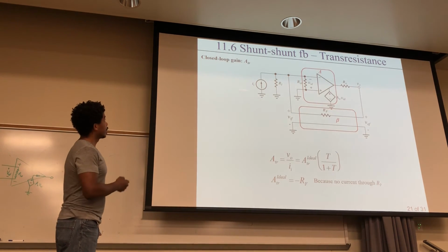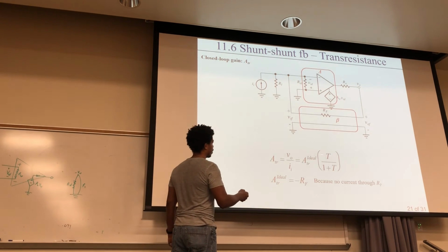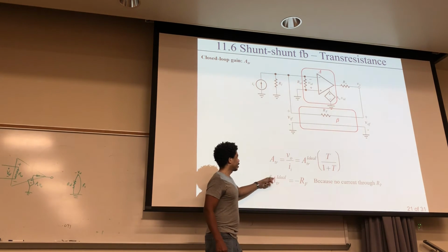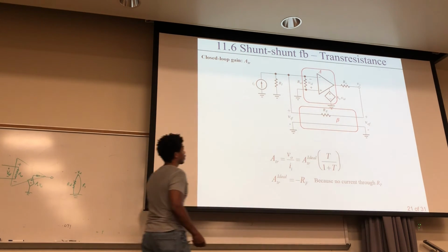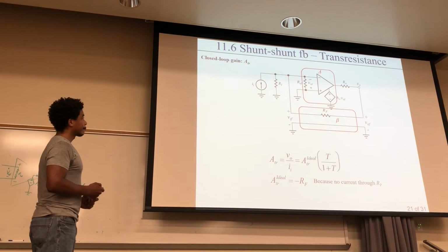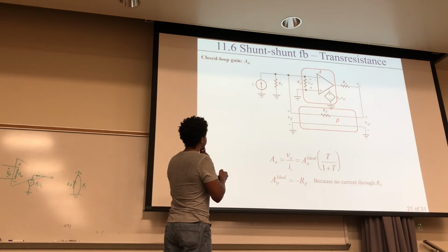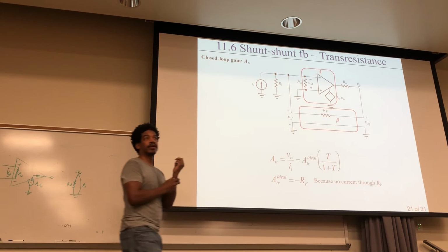Okay, and then again, you can do your closed loop gain. You've seen this formula right here, and we calculated this in a previous lecture. And of course, that is an inverting amplifier, right? You have your negative there, 180 degrees out of phase. And the reason why is because what's the voltage right here across this resistance? RI. What's the voltage drop across here?